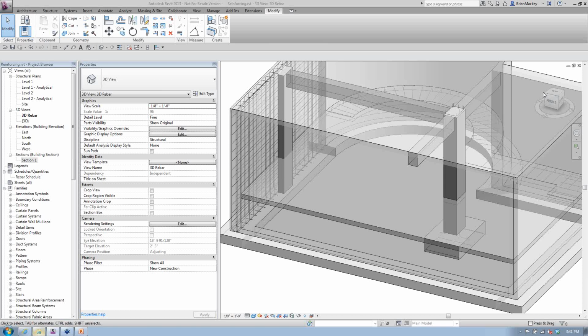A lot of times in something like this, you can see it's parallel. And I try to get in here in places like, man, it's going all the way across. A lot of times I'll just come down here and throw it in at the bottom, as if I was doing cross dowels at the top. And then I'll just take that object and move it to the top because it's already been set up. So you can move it up, you can move it down, you can get it set, you can then stretch it to the cover distances, set it up the way it needs to be set, and it will usually adjust and do what it needs to do. So if you're trying to do a little horizontal dowel in that, you could also choose to change that if you're doing some sort of hook bar at the top.